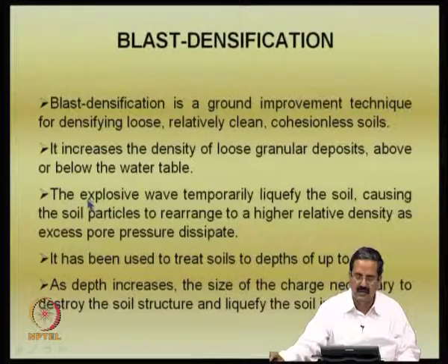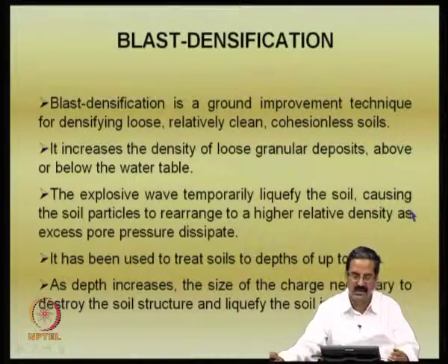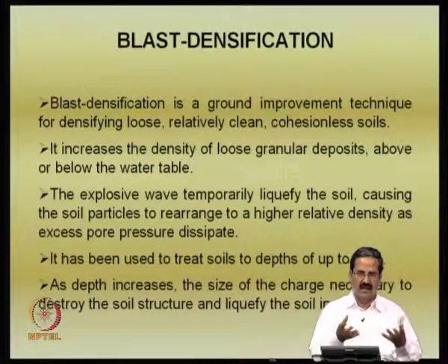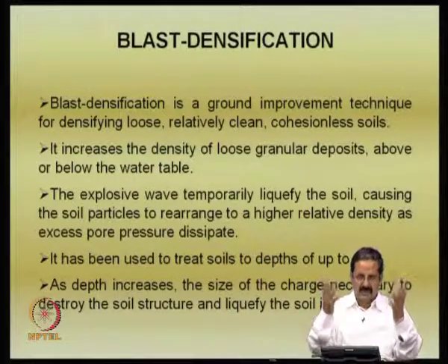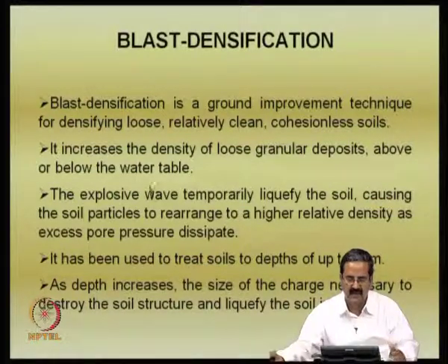In this process what we do is that we try to temporarily liquefy the soil. We liquefy the soil a bit, and then there is a temporary development of pore pressures. This causes the particles to rearrange to a higher relative density as excess pore pressures dissipate. You must have seen the case of a sand boil, in which the liquefaction occurs, then there is a settlement of the ground, and then the pore pressure comes out. Once the pore pressure comes out, that area is slightly densified, and so the excess pore pressures will be dissipated.